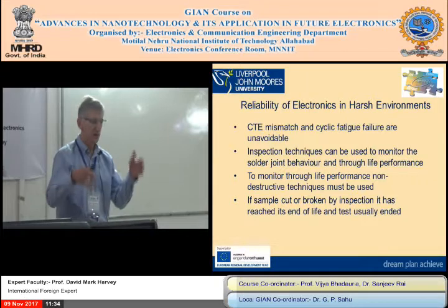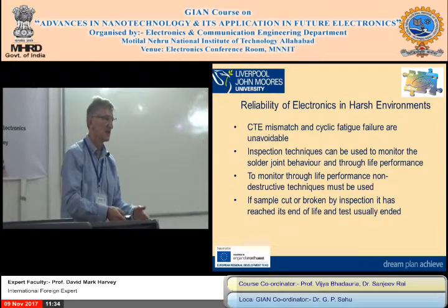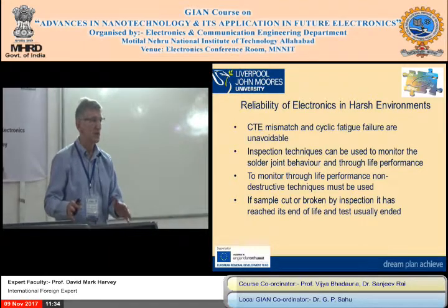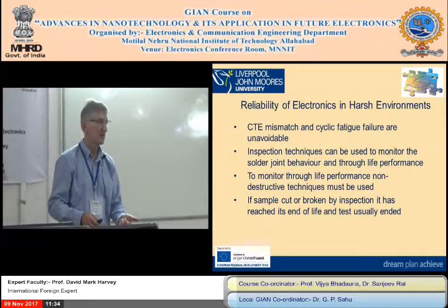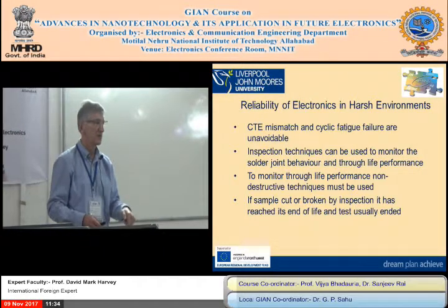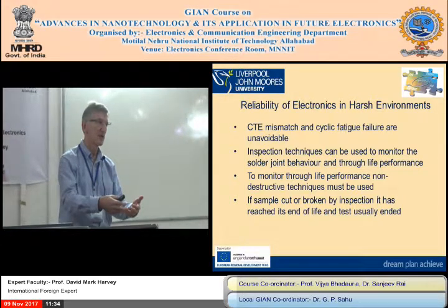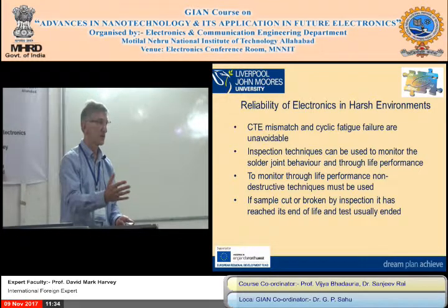Non-destructive testing means you can look at it, and we take it out of the test arena to do that. We look at it and put it back in. We don't break it. So we can use X-ray for that, although some X-rays can damage it if it's too high power, and you can use ultrasound because they penetrate through. Optical, maybe on the edges, but optical can't see inside a ball grid array, inside the solder. And a lot of ball grid arrays are underfilled with the component to make it more stable. So you can't put a fibre optic in there because there's no access.